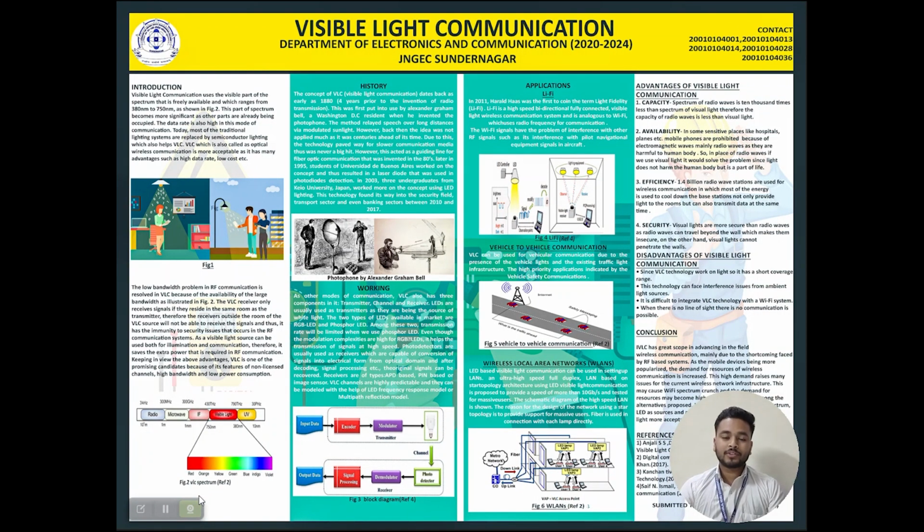Now I'm going to discuss the advantages and disadvantages of VLC communication. First one is capacity. The VLC spectrum is 10,000 times bigger than the RF spectrum, and it has much higher speeds up to 100 Gbps. Now I will talk about availability in some situations like planes or hospitals.